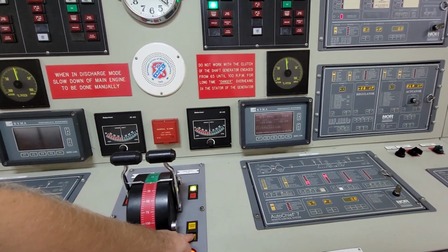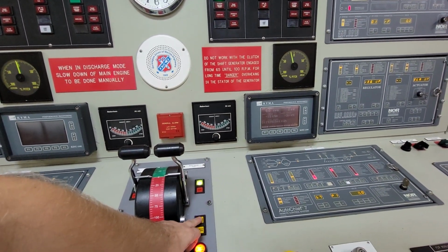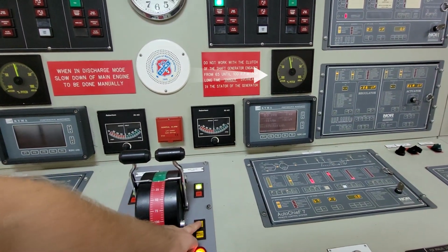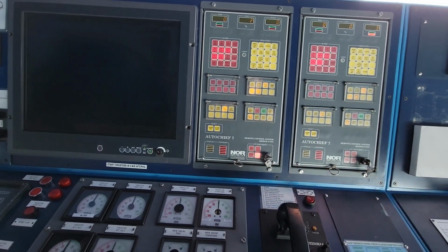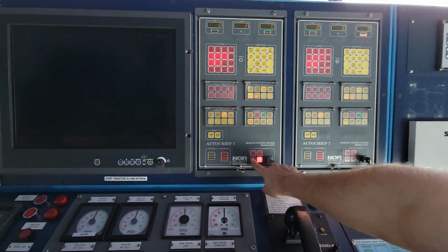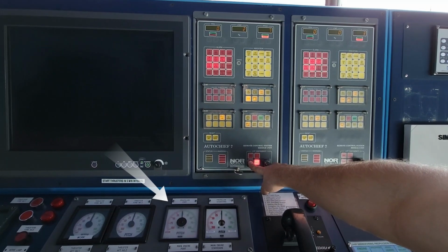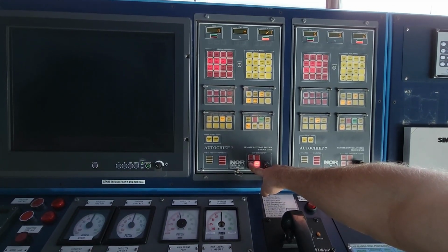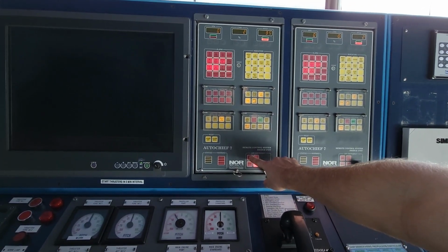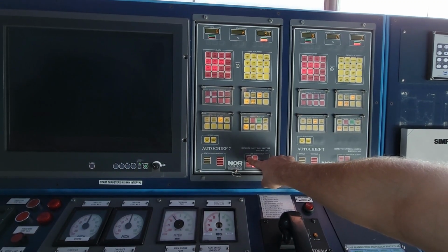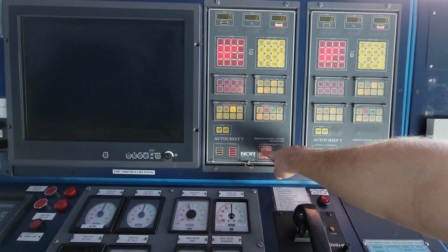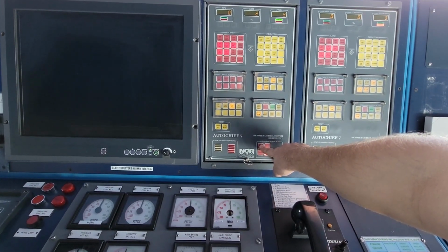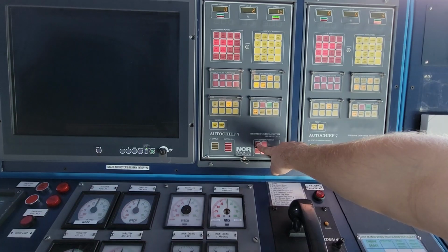In this mode, the pitch control is performed by pressing the appropriate push button, and this can be seen on the pitch indicator. Also, in emergency mode, the pitch can be changed from the panel in the wheelhouse. Using the same push buttons, we can see the changing of the propeller pitch. After some time the emergency mode went out of order and pitch control was immediately transferred to local mode. In this mode, one of the engine crew rotates a special control wheel to the desired angle by listening to commands from the bridge using telephone communication.